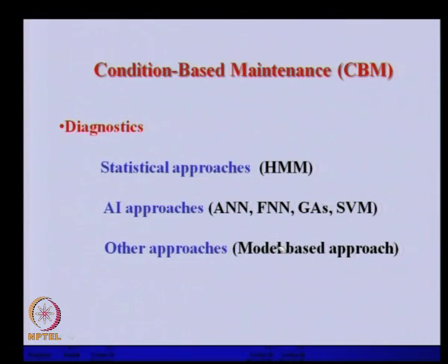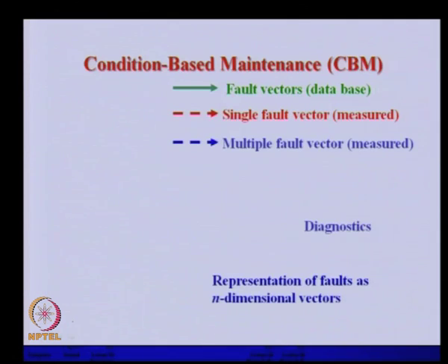Once we measure the vibration from the actual system, we can curve fit the mathematical model with the vibration signal and find out whether the fault is there, and if it is, how severe it is, or quantify the fault, with the model based approach, which is real research taking place at present in the rotordynamics field. So, this is a very abstract way of how we can diagnose the fault.